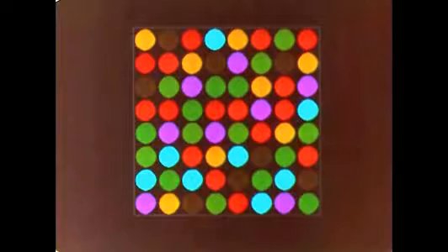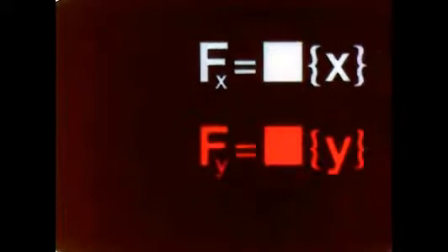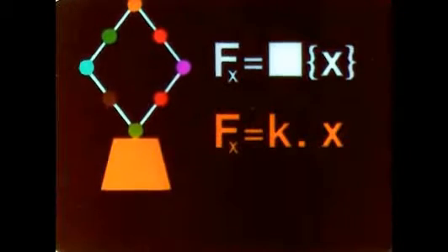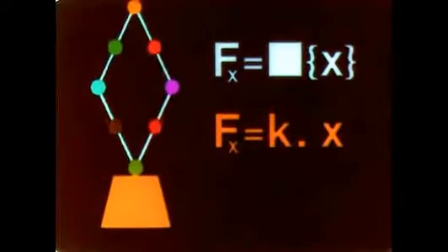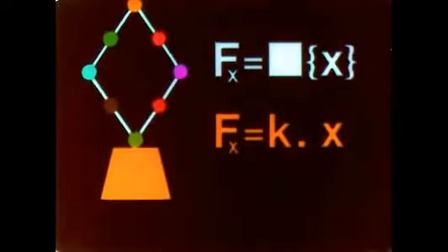This matrix is now the starting point for a series of steps based on the fundamental laws of mechanics. Step 1 relates displacements to stresses. From stresses we obtain strain energy, and from this we derive potential energy, and finally, from minimum potential energy, we obtain a pair of system equations for the complete element. By analogy with the equation of a simple spring, this new matrix is called the stiffness matrix for the element. Instead of a single displacement x, the matrix operates on the vector x, whose components are the displacements for the whole element.